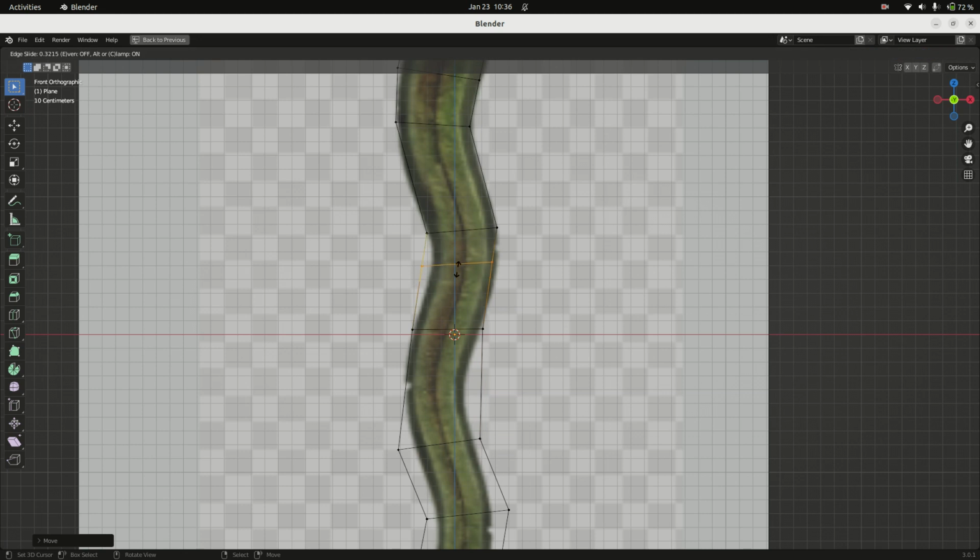So when I left click there, I now go into, now where do I want this to lie? I can hold Control and I can snap this. You can see there's a little highlight changing to show me where I'm at the midpoint, because oftentimes we want the midpoint. And right click will cancel the move, and then Control Z will undo. Control R to loop cut, left click to confirm the cut position, and now I have a little bit more geometry to work with.